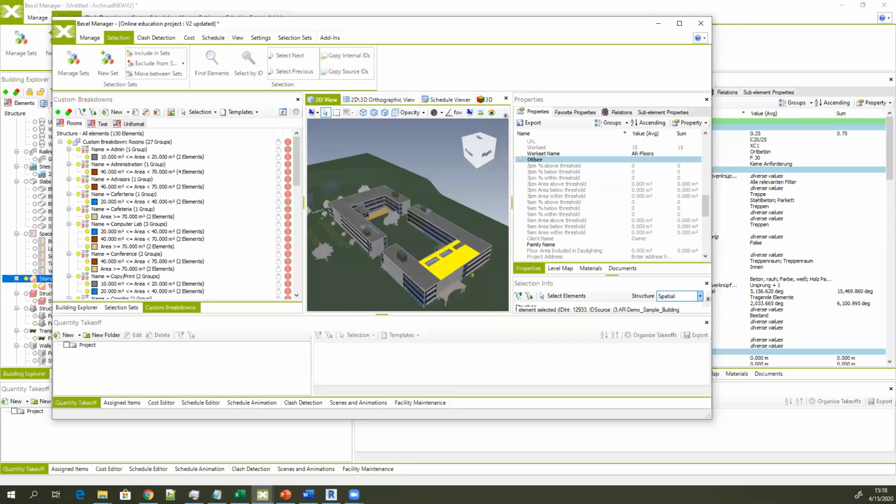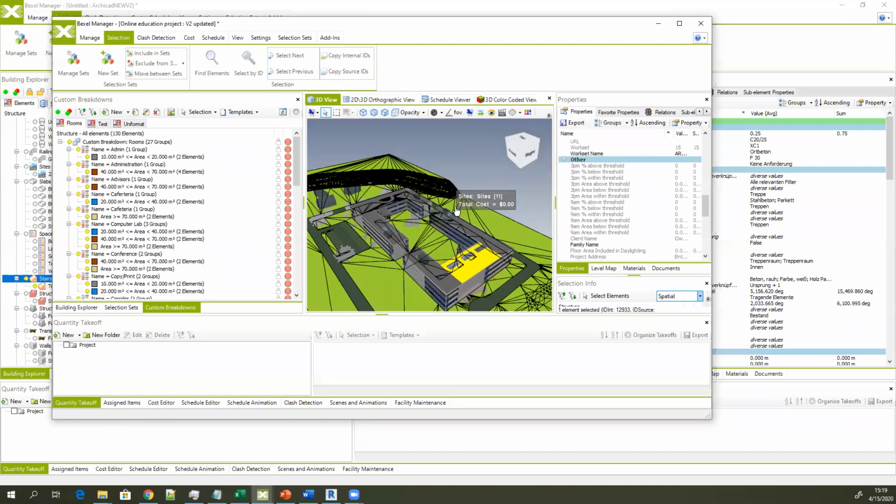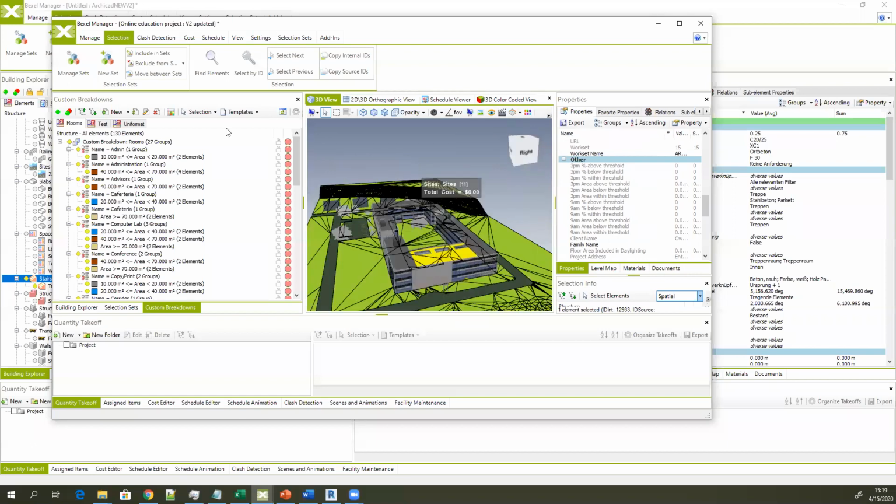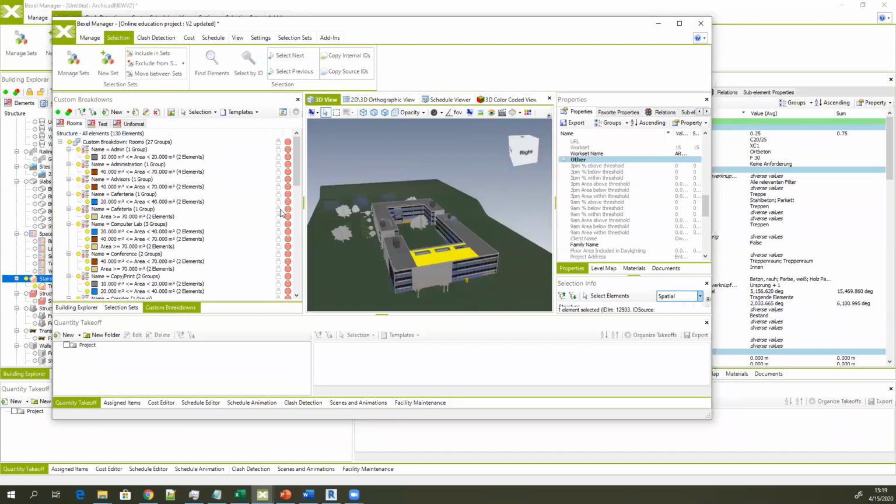Is there any such example available using projects like roads or tunnels instead of buildings? Currently, according to the IFC standards, every project is automatically segregated according to the site, then building, and then building levels. So if you have, let's say, tunnel projects, and hopefully you remind me, I'll try to show that in the next presentation. Even if you have a tunnel, you're always going to get the building, because it's something that is standardized, and you can always rename that